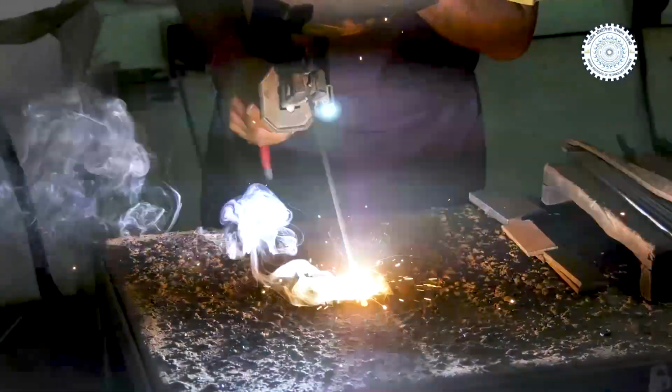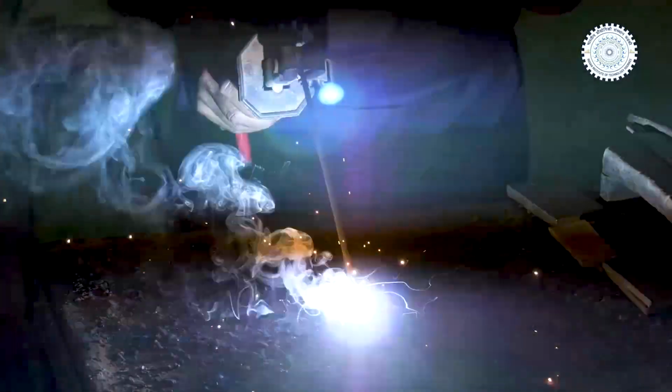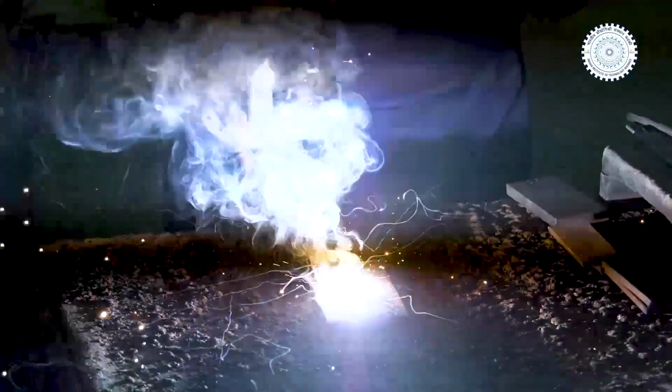This is the tagging process, the tack welding process, where we try to maintain that arc. Now, this is the welding process only. Here, in a very controlled way, the arc is being moved along the weld line, so that there is a proper deposition of the molten metal as well as the through thickness penetration is also realized.